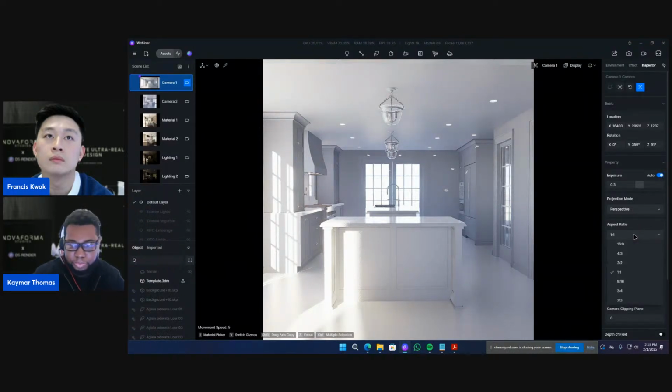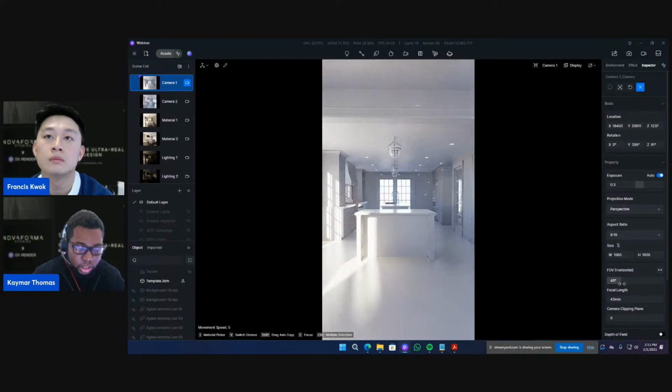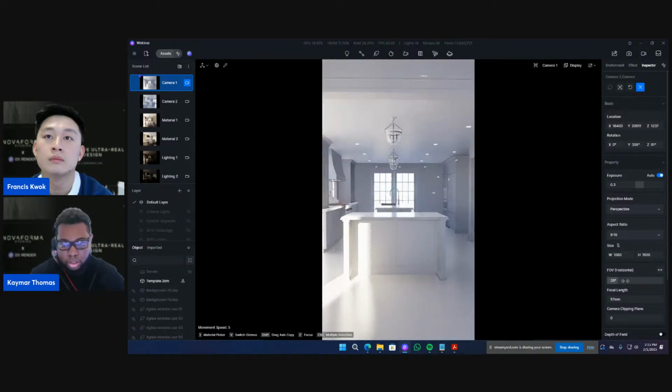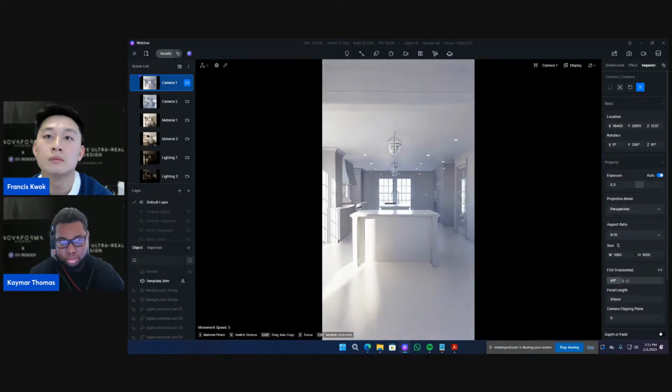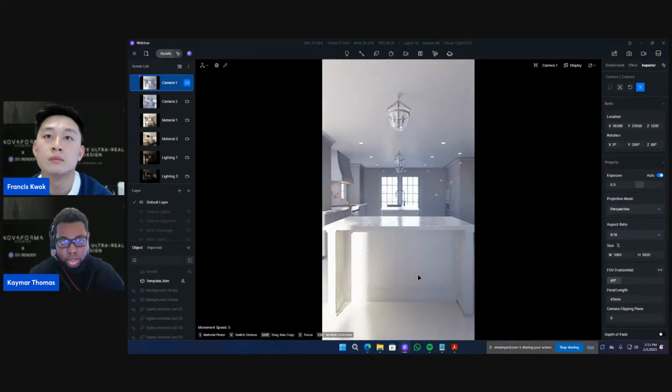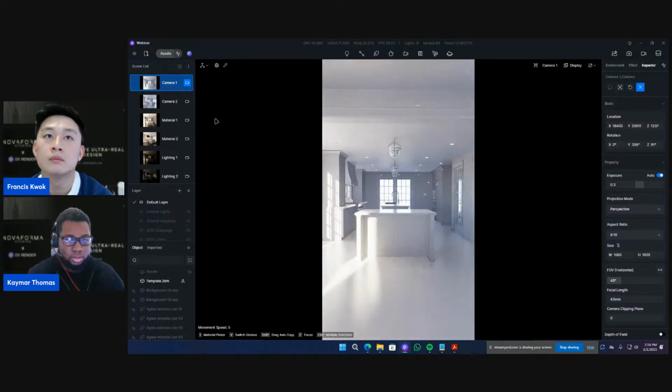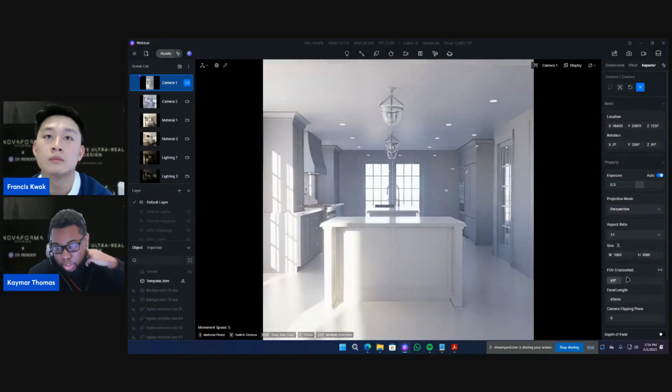If you're doing portrait, which we sometimes use when we want to post on Instagram or social media, we go even lower, around 45 exactly, and then we zoom in or move the camera further to get that. So that's the workflow logic for field of view. Going back, we keep aspect ratio one-to-one, field of view of 45 for this camera angle.